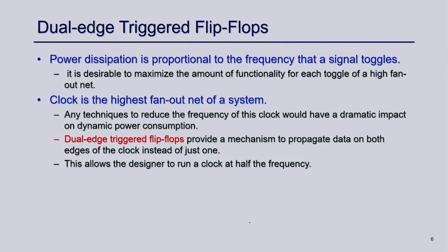Okay. The third technique we are going to talk about is dual edge triggered flip flops. What is that? We have seen that power consumption is directly related to the number of toggles in your design, right? So, if you find some high toggling signals, which toggle in every clock cycle, for example the clock itself, the clock always toggles.